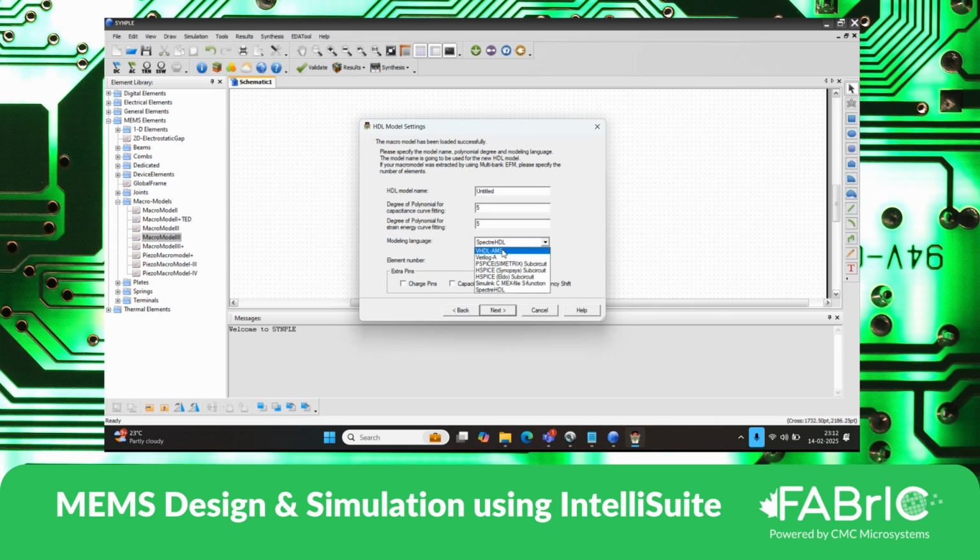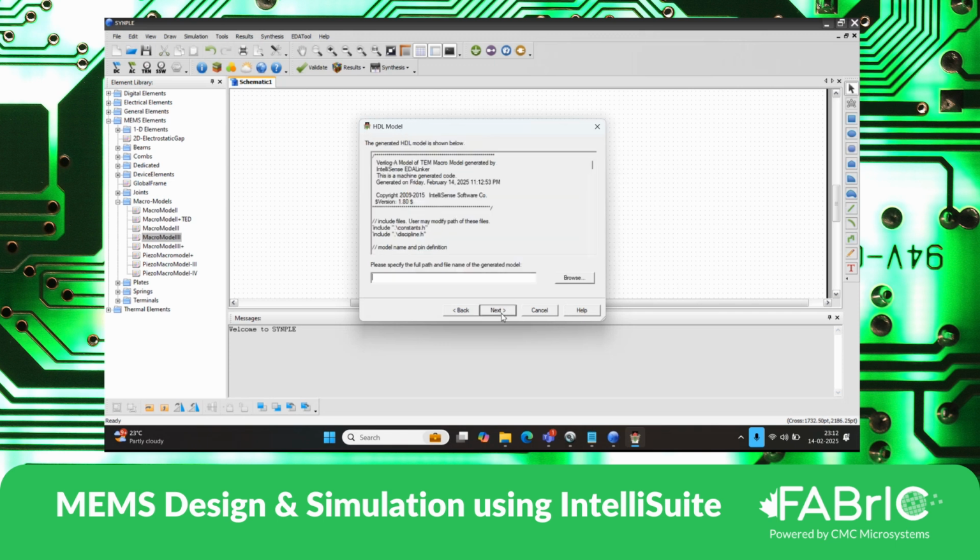You want to convert this MEMS device file to a VHDL file or a Verilog A file or a PSpice, HSpice, Simulink, Spectre HDL. So you can do that. So here, whether it's VHDL, Verilog, you can always use Synopsys, Cadence, Mentor if you are a user of it. Let's take the Verilog, and then I would say CPS, capacitive pressure sensor, and then click OK.